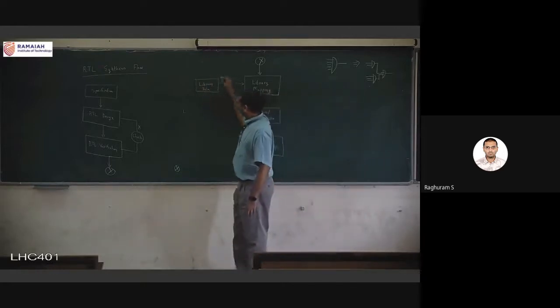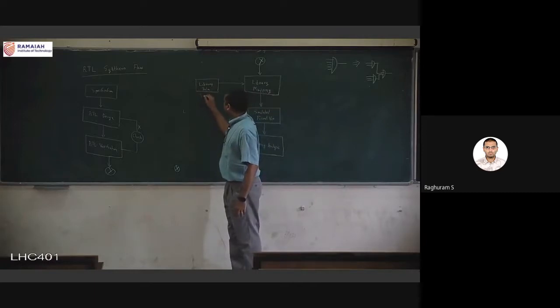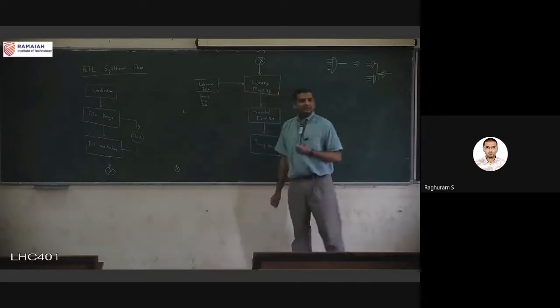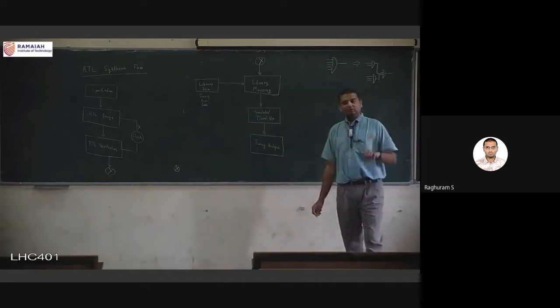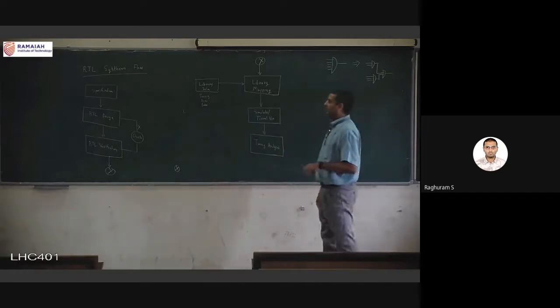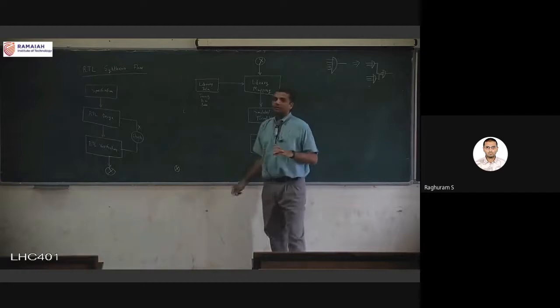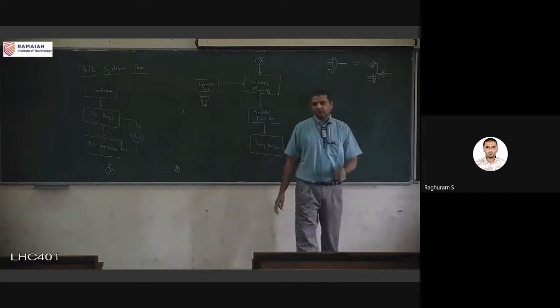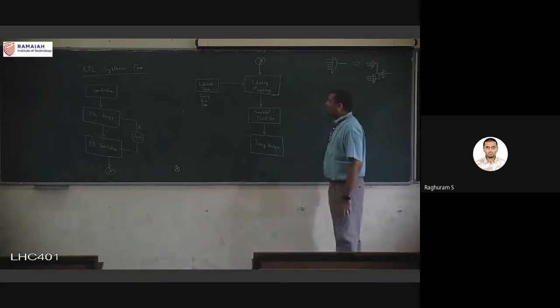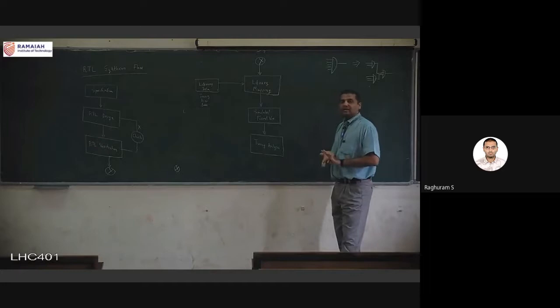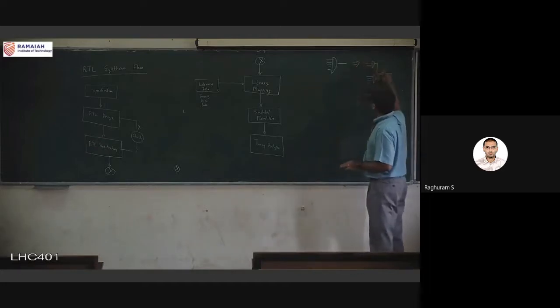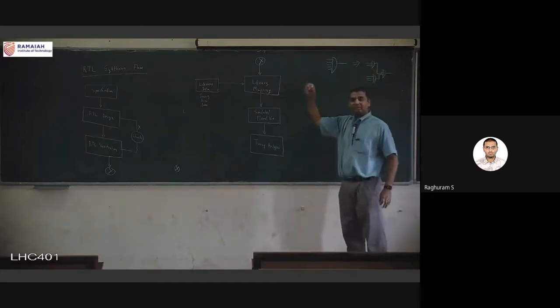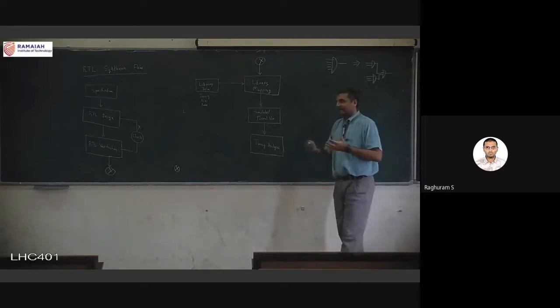It's because of this library: timing, area, and power. So these are the things that are also available as part of the library data. It's not just the functionality. It's not just the 2 input gate or the 3 input AND gate. It is also the timing, power, and area information of each of these cells. Some engineer has sat and done this.